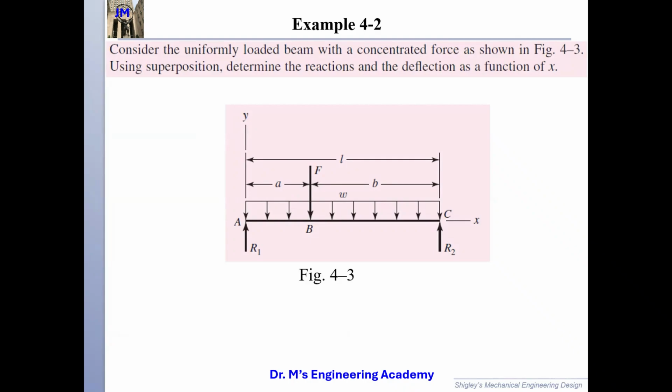Guys, to know how to do the superposition, the assumption is that the material is elastic and the deformation is small. Small deformation means that if you apply one set of loads, the results will not affect the results when you apply another set of loads. So this is small deformation, elasticity. If these two assumptions hold true, superposition will work very, very well.